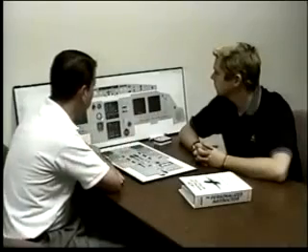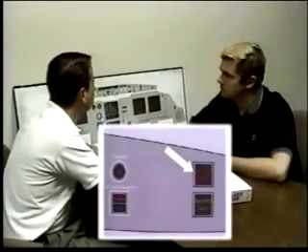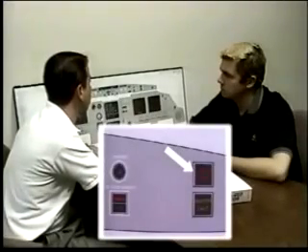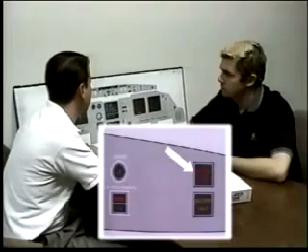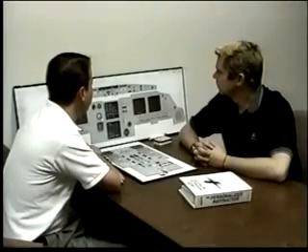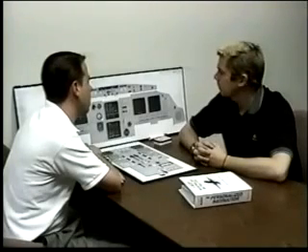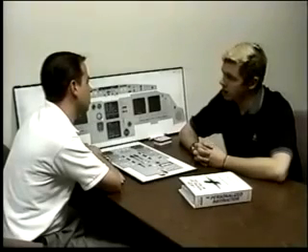A red master warning. You get a red master warning, repetitive chime, and this is a level 3 ECAM. Are there some times that you might have an inhibit of master warnings or even certain ECAMs? Yes, there's the takeoff inhibit and the landing inhibit.